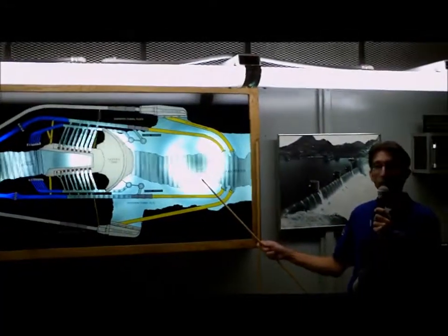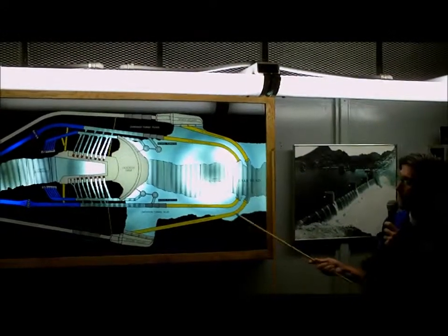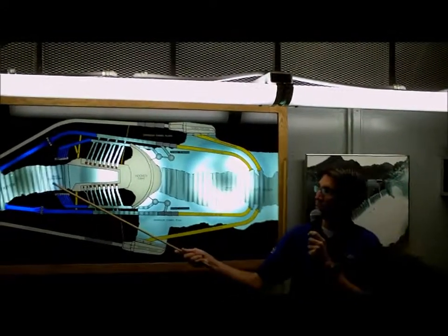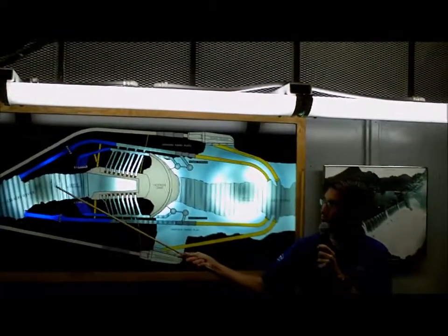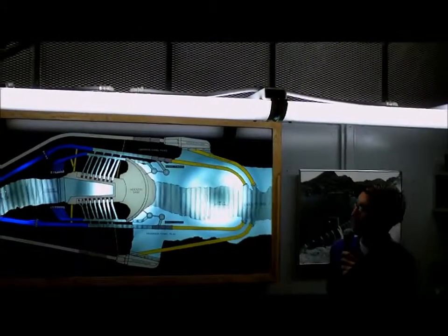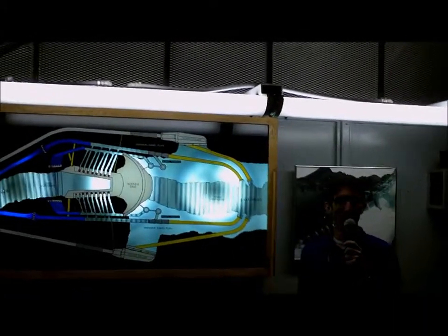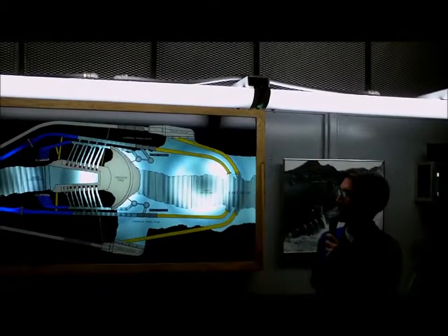An upper coffer dam, or earthen dam, was put in place, and that was to encourage the river flow into the new tunnels. And a lower coffer dam was built to prevent the backup of the river into what would become the dry construction area of about a half mile. So we'll get to that in a minute, but they put another generator online just right now. That's what that water rush is.